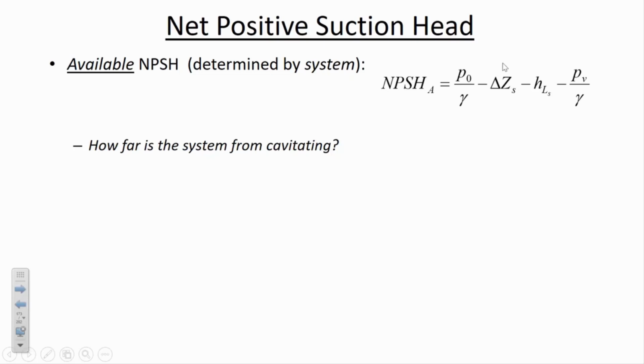If you have a big elevation difference, meaning the pump is lifting the water a big elevation from the suction side to the pump, that means there's going to be a larger negative pressure, in gauge terms, below atmospheric pressure before the water gets to the pump. Or if you have a really long suction side pipe, you're going to have large head losses. A really long suction side pipe increases the risk of cavitation, because it's spending the currency of this atmospheric pressure.